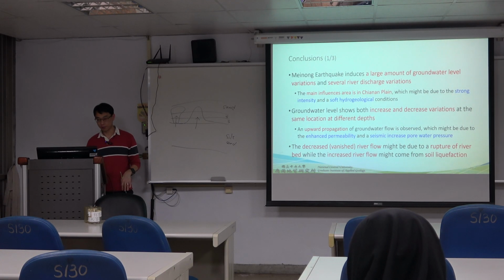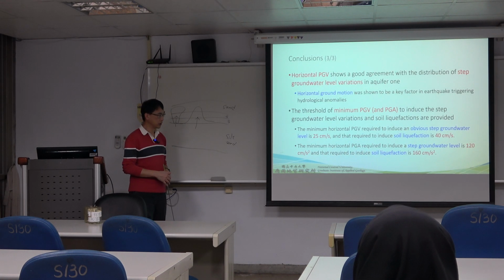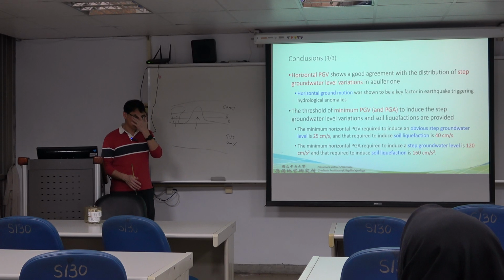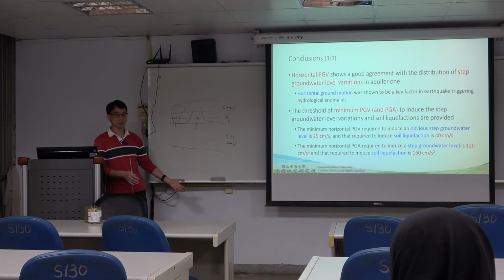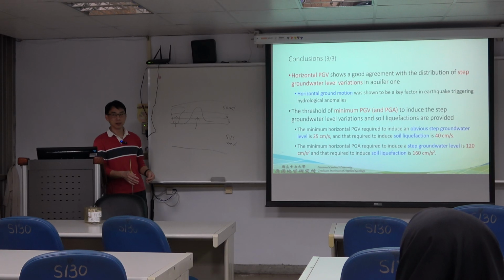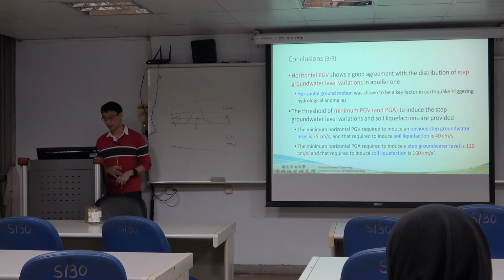Okay, so this is just one example. And for the conclusion, I think the most important part is that in this study, we try to address that hydrogeology plays a very important role. We cannot just use an empirical concept or just a regression concept to do a lot of analysis. We need to consider the hydrogeology or geology concept, and we need to even consider the topography influences. It is not only the distance. If you use the distance, that means you ignore the other influences. Like I mentioned, the rock system and the sediment system, you cannot combine them together for the comparison. It's not correct.